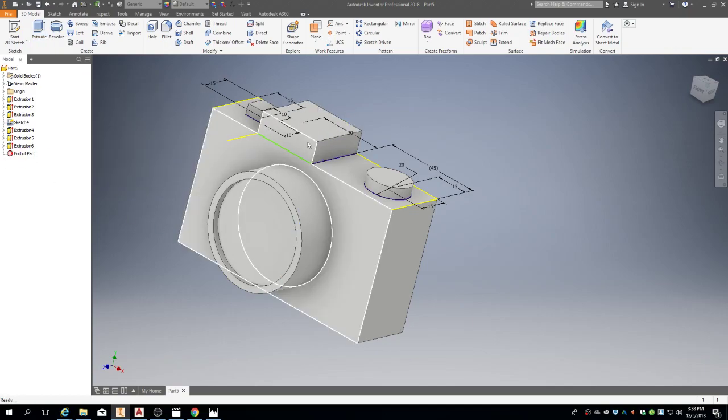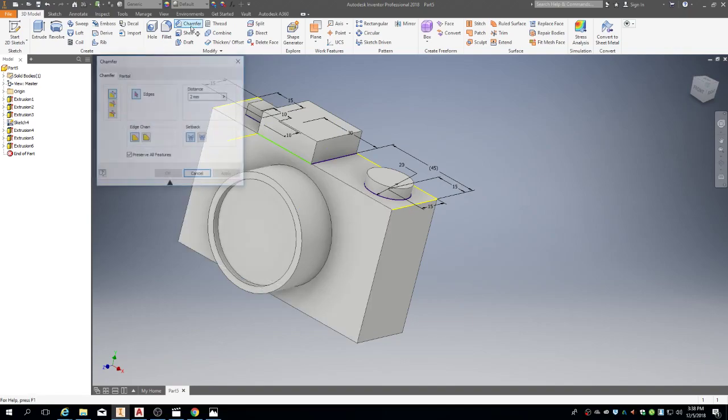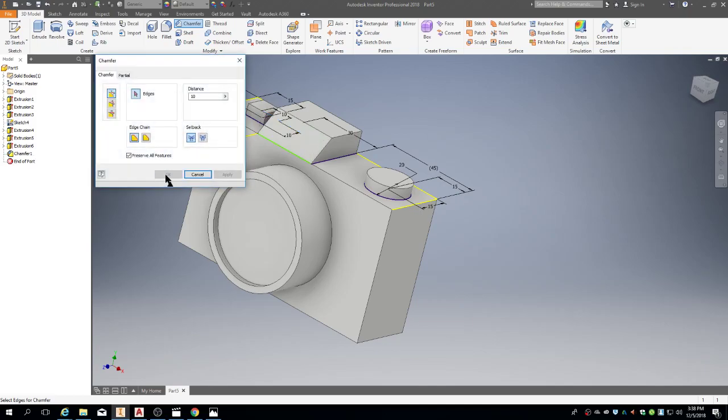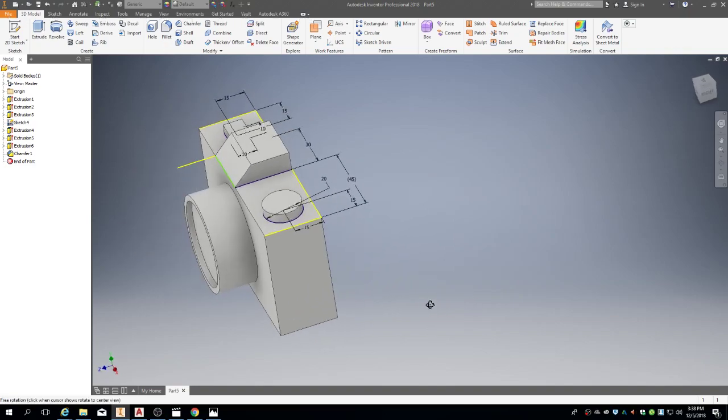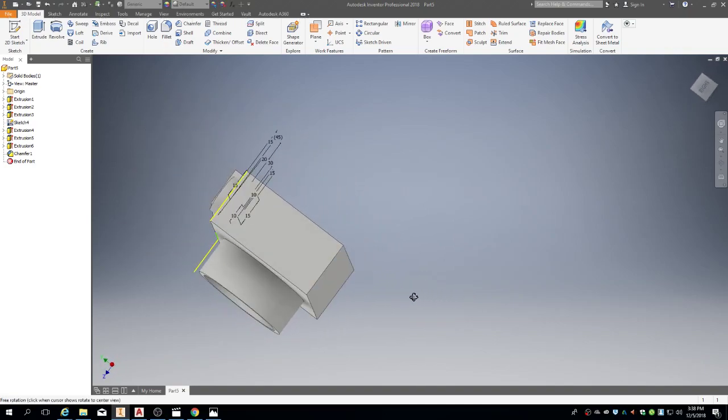And that's by using the chamfer button. Chamfer at the top, set it for 10 millimeters because that's how tall that object is, and simply go in and pick that edge, and it will chamfer it off. Okay, we've got everything we're looking at here.